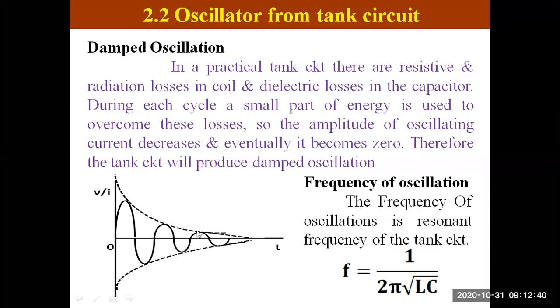Due to this decrease in amplitude, after this oscillation travels a certain distance, the amplitude becomes zero, and therefore this tank circuit produces a damped oscillation.